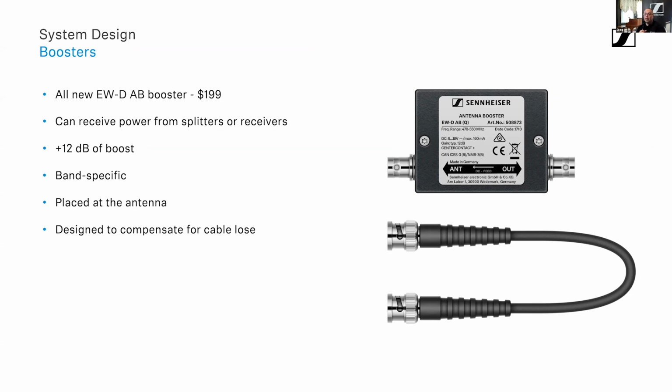For example, I have 25 feet of RG58 cable running to my ADP UHFs, which we're going to use here, and I get about 3.4 dB of loss. Now, I could have used a better cable to get less loss, which would actually give us more range in our test. Fortunately, I didn't have a different cable, so this is what we're going to use. But 3.5 dB is still going to get us a significant amount of range, which you'll see here in a minute. But if I was using 300 feet of cable, even if I use some of the highest level cable, LMR 400 cable or 9913 cable, it's still going to provide a significant amount of loss.